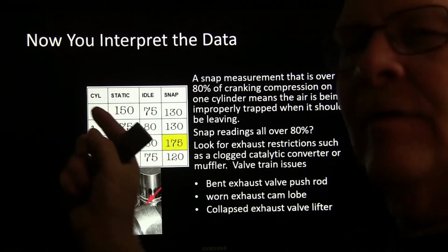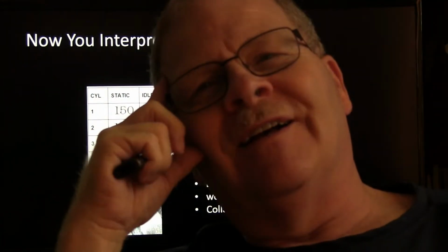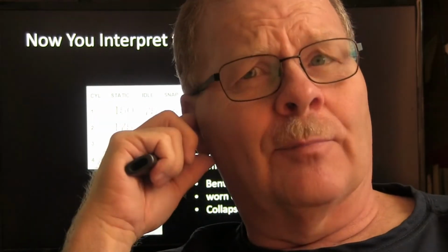These rounded off camshafts used to be something that were pretty prevalent on Chevrolet small block Chevys. And my dad, one time for $400 or $500, bought a '77 Caprice. It had a 305 in it, and it had a rounded off camshaft. And when a camshaft was rounded off, with a carburetor on it, when it was running, it would go pop, pop, pop, pop, pop, pop back through the carburetor. The exhaust valve would be rounded off, and the exhaust didn't have anywhere to go, but it would pop back out the intake, and that was a camshaft issue.